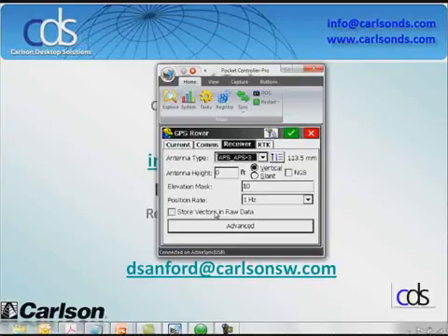This is a new option. To me, it's kind of like having your angles and distances in your raw file from your total station. Instead of simply saying, here's my latitude, longitude, I actually have something I can post-process against, and I can actually use those measurements to recreate all of the survey data from the base position. So the raw vector is a nice thing that they added in. I know a lot of people have asked for it for a long time, and it was really nice to see it in the 2.0 releases of SurvCE.